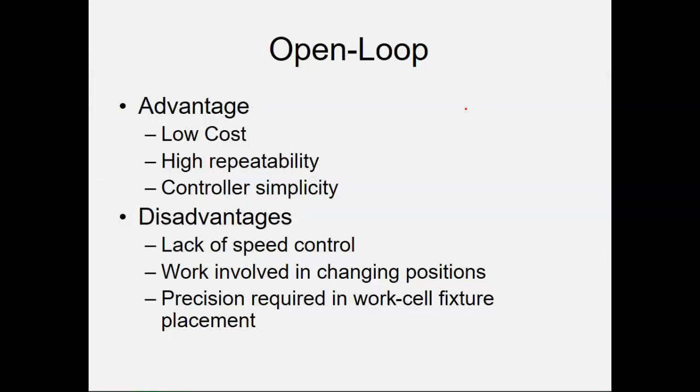Very good. So the advantage of open loop is low cost with high repeatability and controller simplicity. If you just need something that's cheap, quick and easy, and it's a repetitive job that's not going to change, open loop's the way to go, right?